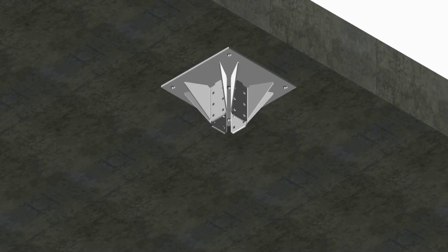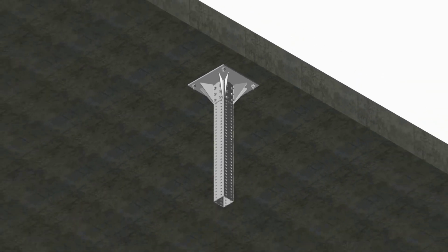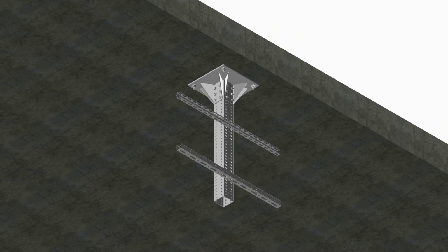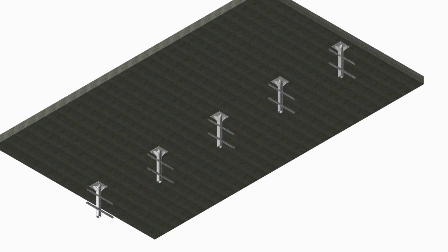As you could see, MT System gives the opportunity to use material efficiently. For parts of the application being exposed to heavy loads and bending moments, use the heavy boxed profiles with sufficient base material connectors, and for the parts exposed to lower loads, use smaller economical profiles fully compatible with the heavy ones. This gives us an opportunity to be price competitive.